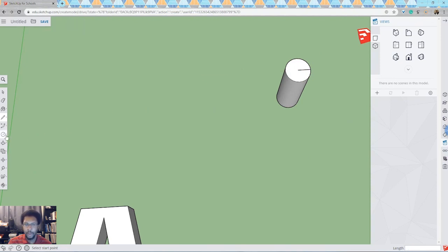So we can go back to the circle tool over here, and then go back to the 3D object, and you can see it snapped to that endpoint before. I found when I'm personally using SketchUp to do modeling, that if you don't do this, sometimes the mouse doesn't find that endpoint or the center point of the circle if that line isn't there. So by putting this line there, it makes it find it much more easily compared to if it wasn't there.